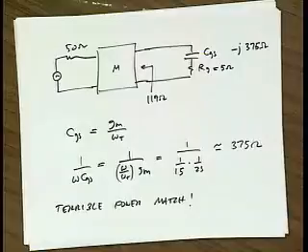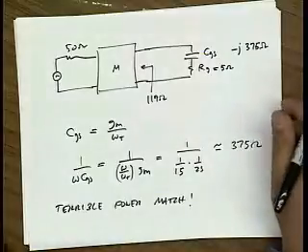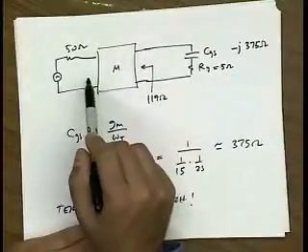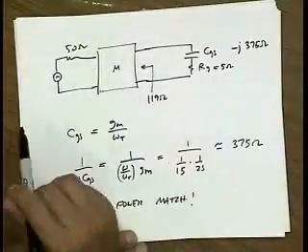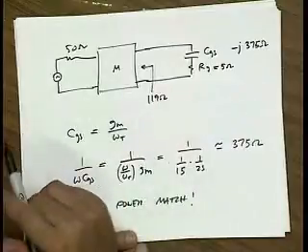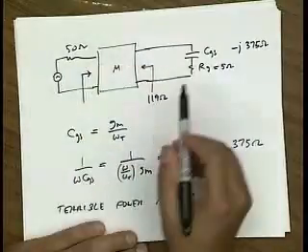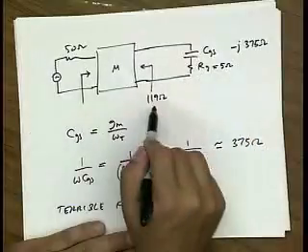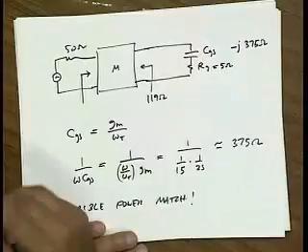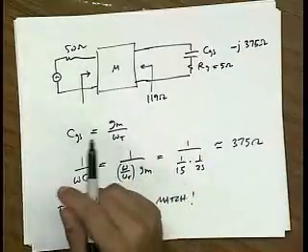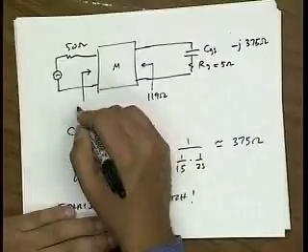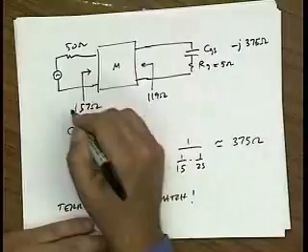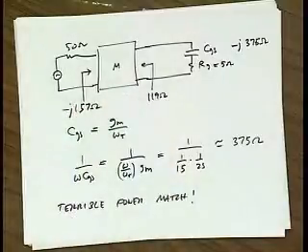In fact, there are several reasons why it's not practical. First of all, you don't hook up the input directly to the antenna. You usually go through a filter, and that filter needs to be terminated with 50 ohms in order to work. What does the filter see? Well, the filter sees this impedance transformed down by the ratio of 119 over 50, which is about 2.4-ish. So looking into here, I see about 157 ohms, but minus j, capacitive.